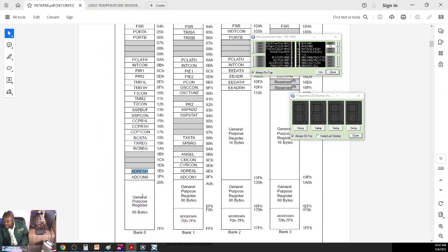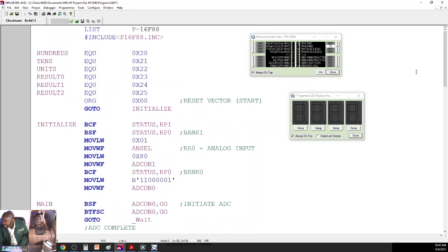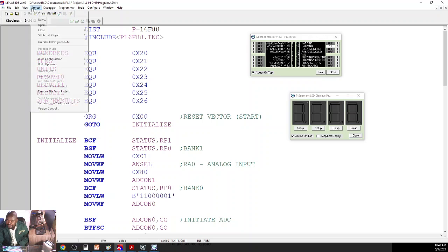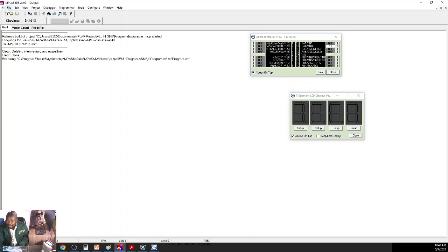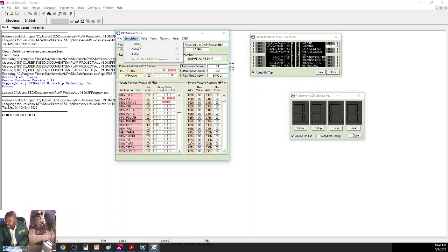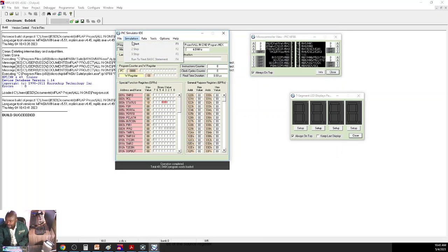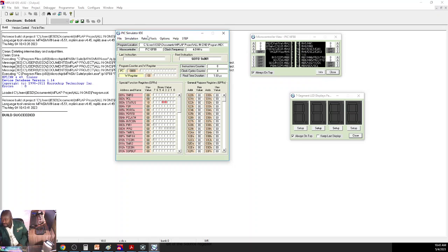That will allow me to access it in bank 0. So let me go and say address H can be my last general purpose register equated to memory 26. Right. Let's build this quick build and see what happens when you simulate it this time around. That might have been the only error, could have been one of the errors.